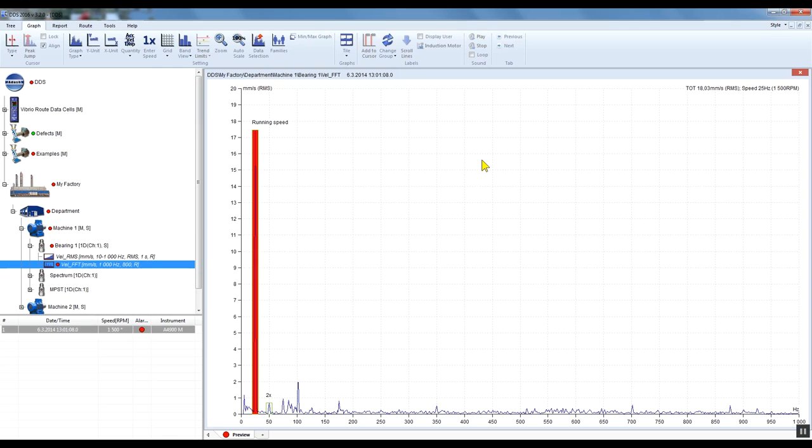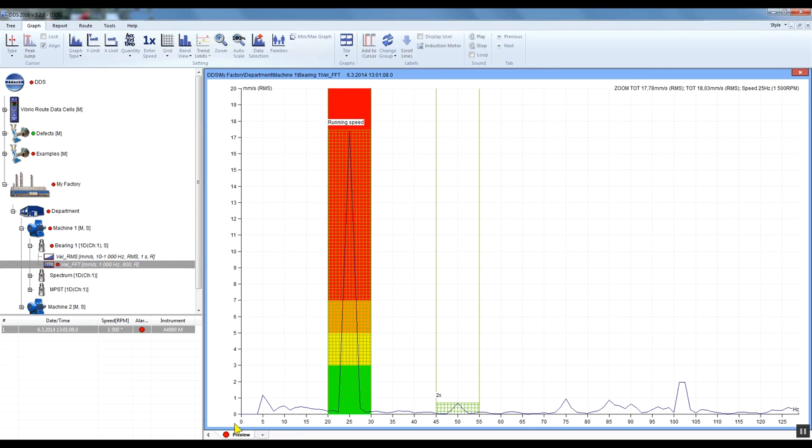To see all my limit values applied to graph, go to the Graph tab, click on the band view and select the With Limits option. Now you can also change the limits using the mouse. Simply drag and drop the limit value which you want to change. If you want to hide all the defined bands, go to the Band view and select Off.